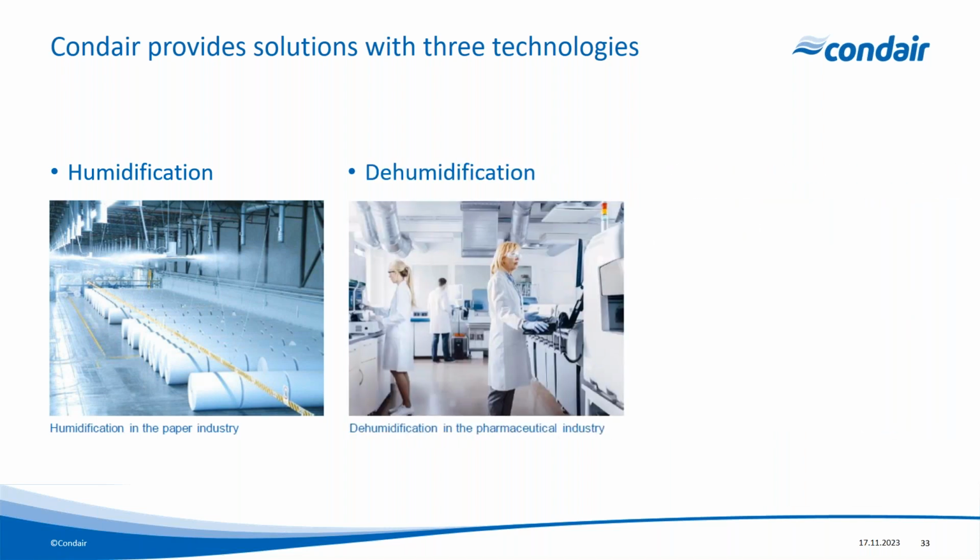We offer dehumidifying systems, so we offer technologies for higher relative humidity, higher temperature applications where we use condensing direct expansion refrigeration systems, or we also get involved in low moisture content applications such as a cryogenics lab where we want very low relative humidities, and we use desiccant technology for that.